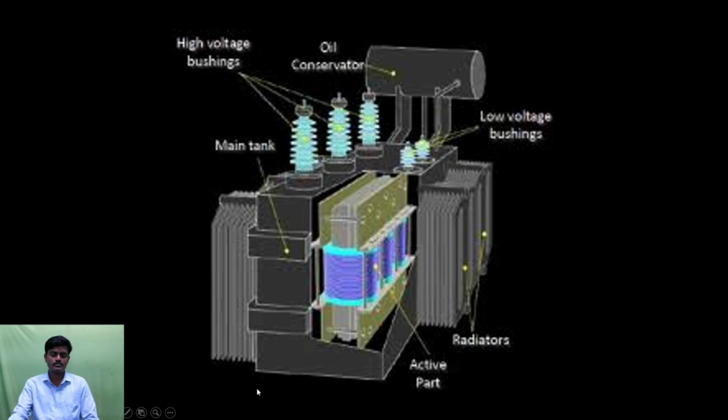This power transformer is mainly used at the substation level, not on the consumer side. It needs weekly, monthly or daily maintenance, based on what we are considering. Here we have the oil level gauge, temperature gauge and pressure gauge. Based on those, if maintenance is needed, we have to do it then and there. So this is the power transformer diagram.